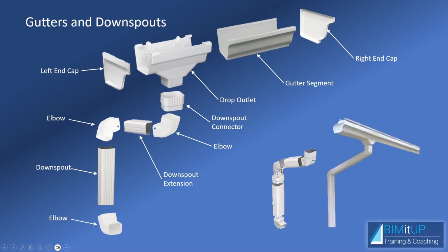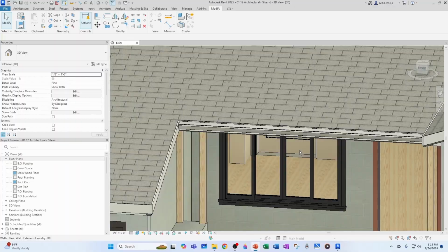And for this, you have a couple of options. You could use a pipe, a round pipe, or in my case, I think I'm going to use a duct, even though it's not specifically a duct. It is a PVC channel, but I can do a duct. You could use an oval duct, or you could use a rectangular duct. I think the rectangular duct is what's going to resemble it best. So let's give it a shot. Let's go back to Revit.